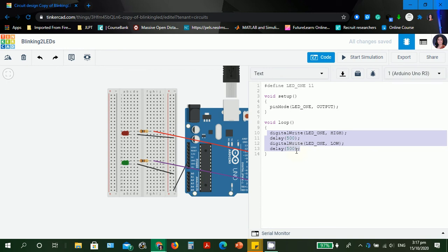Unfortunately, Tinkercad does not have the tab feature. So what are we going to do? For example, if you are given an Arduino sketch in tabs, the technique here is just to include it all in the main tab. So let's encode it one by one.